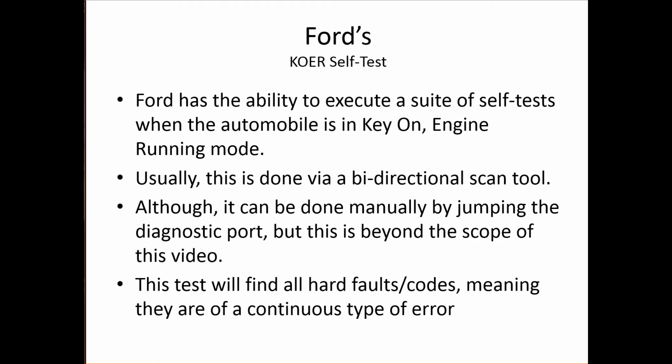We did that, but unfortunately that test only tests the purge solenoid. Doesn't really test a full test. So we had to wait for the full readiness monitor. So again, the key-on engine running Ford self-test really just looks for hard faults.